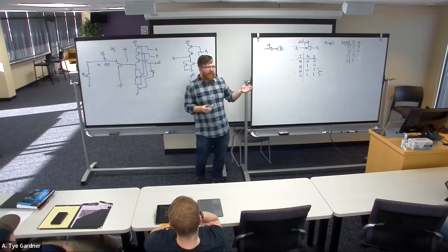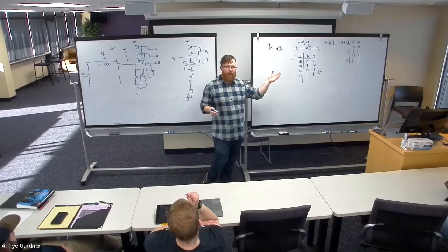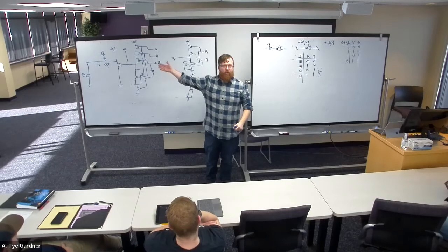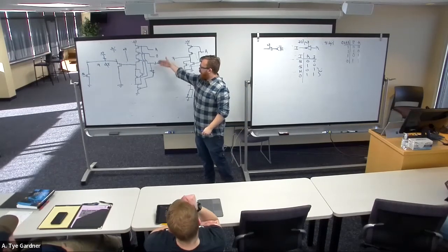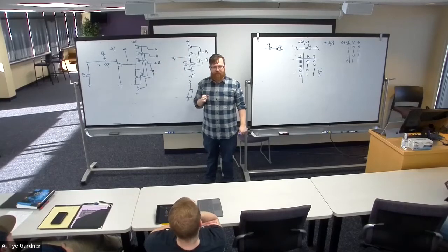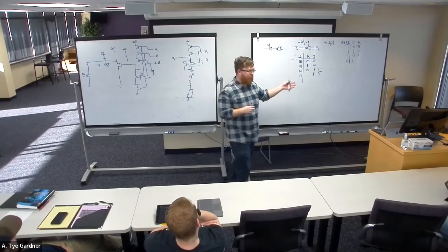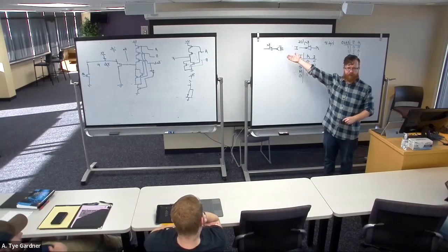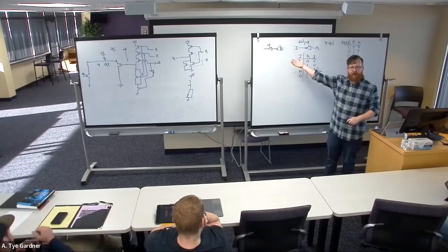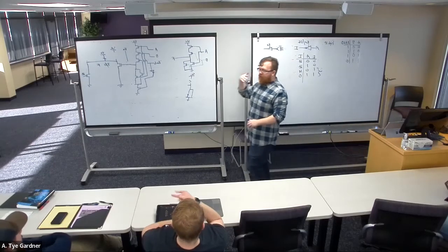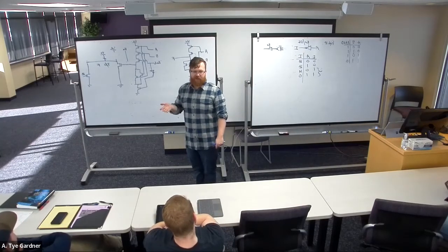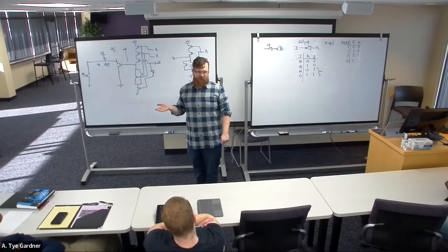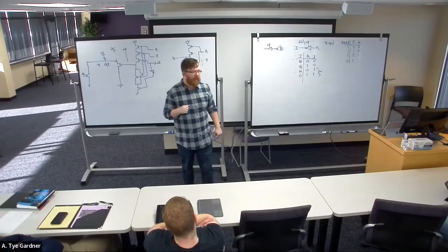Yeah, so it turns out this is why these active low signals are important to know, because sometimes active low is the easy way to build something. Because if I wanted to turn this into an active high enable using this architecture, I actually need 2 more transistors, right? So depending how you want to build your architectures, it sometimes makes more sense for the enables to be active high or active low. A nice rule of thumb is, if the signal is part of your data, then it is going to be active high. If it's part of your control, then it's active low. Not always, but generally that ends up being what happens.